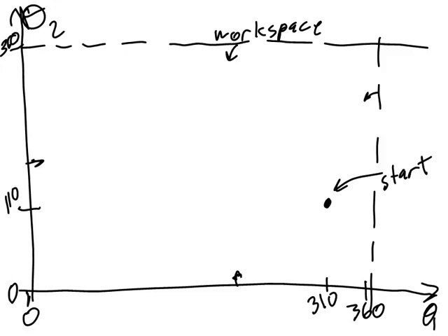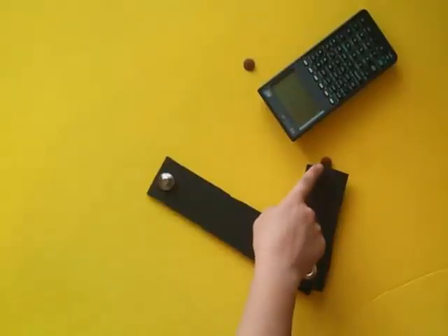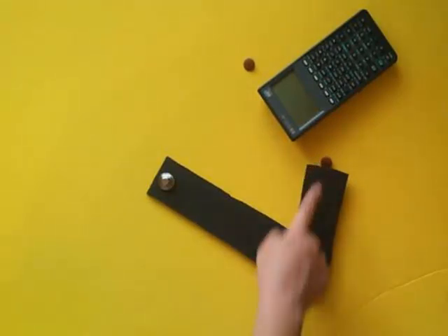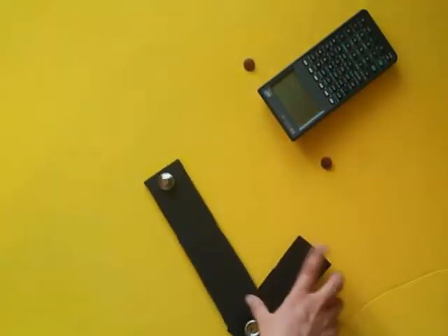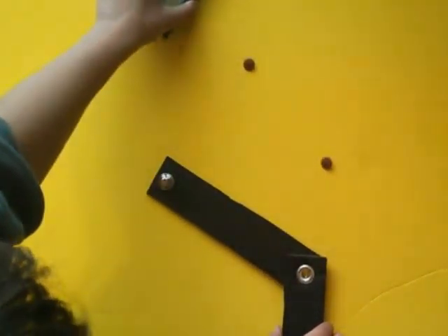in configuration space. Note that when you use the inverse kinematics to calculate the start and end points in configuration space, there is likely to be more than one solution. These two solutions are known as elbow up and elbow down configurations. For example, the end effector can go to the start location either in this configuration, or I have to ignore my obstacle here.